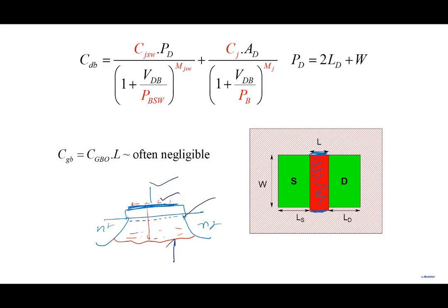So that's where there is no area component of the capacitance. So you're left with some fringe lines here and here between the body and all that. So this is where you have only this particular capacitance here. So often it is a negligible part of the capacitance. Gate to body is the smallest component, and many times in simple analysis we often just neglect it altogether.